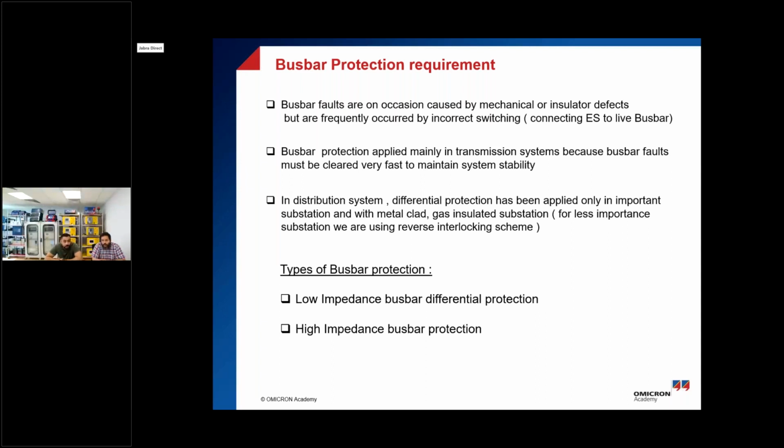It depends on Kirchhoff's current law. And Kirchhoff's current law says that all currents entering any protected zone should leave it, or the total summation of the current in plus the summation of the current out should equal 0. This was taking into consideration the directionality: the current into a protected zone should be positive and the current leaving the protected zone should be negative.